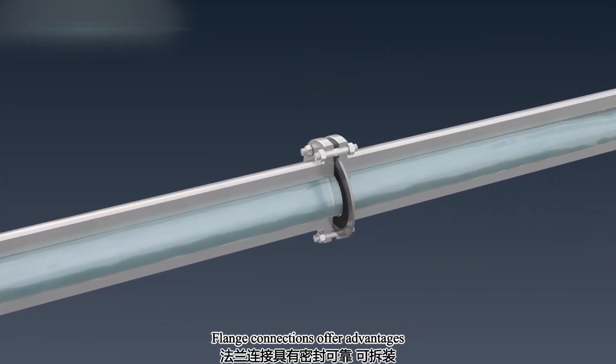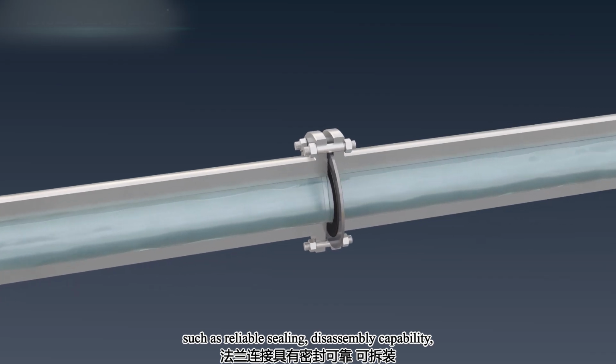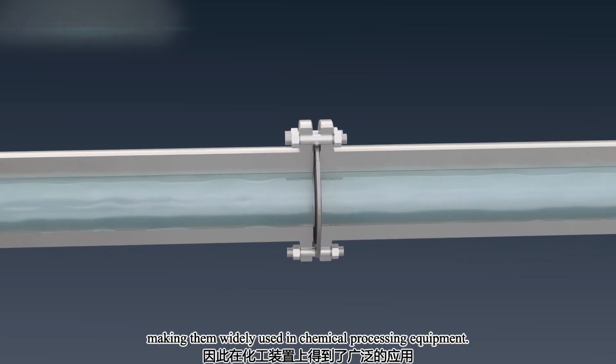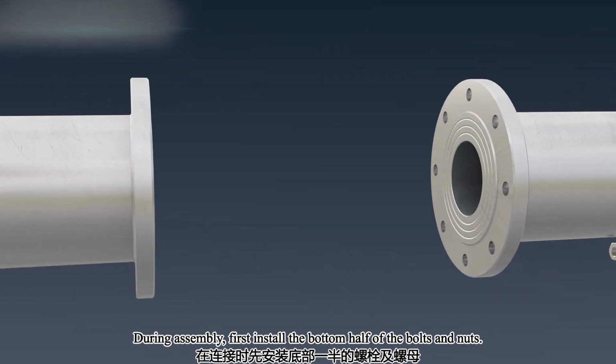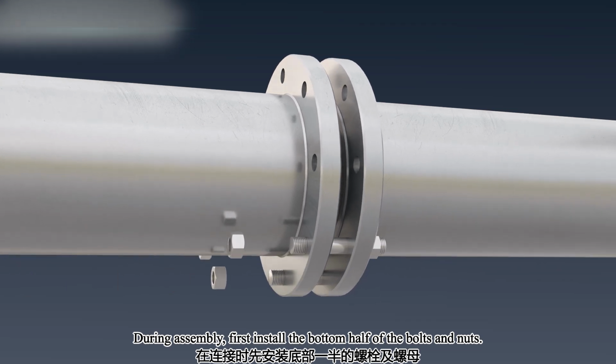Flange connections offer advantages such as reliable sealing, disassembly capability, and wide adaptability, making them widely used in chemical processing equipment. During assembly, first install the bottom half of the bolts and nuts.